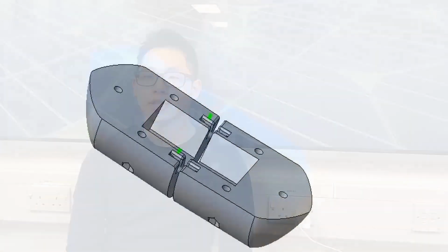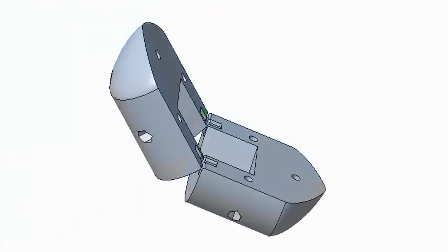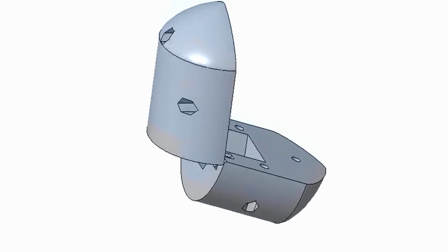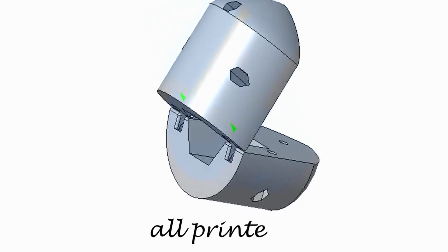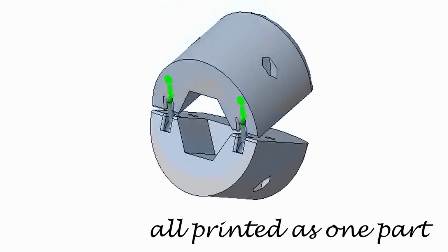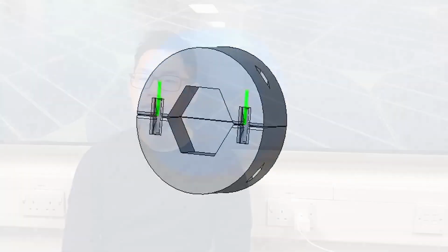After exploring a range of different hinge designs, we chose to use 2 ball-and-socket hinges to connect both parts of the hub together. The simple design, which comprises simple geometric shapes of 2 spheres and a cylinder, made it relatively easy to model and create. Furthermore, the ball-and-socket hinge would be hidden within the hub in the final turbine assembly, and as a result, would not affect the flows around the hub.